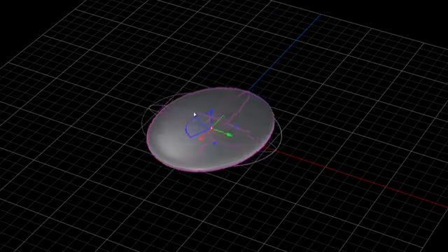Why I bring that up is you'll also notice here as I rotate my viewport around, you'll see this little box right here. And half of that box is bright green, the other half is red. What this little button is, if I click and drag on it, this is a 2D move. Again, if you've used the T-splines HUD, you notice they always have a little flat disc that you can use for a 2D move. So Rhino has, with their gumball, color coded it so you know exactly which two planes that you are moving this in.